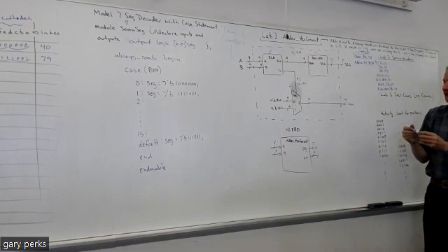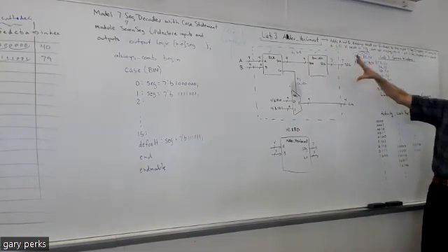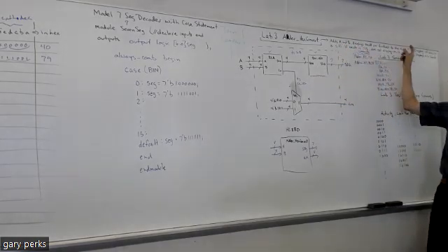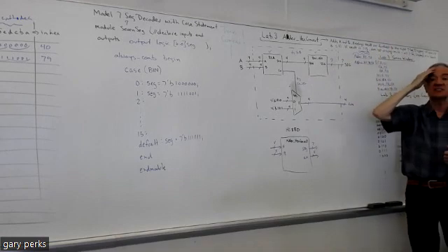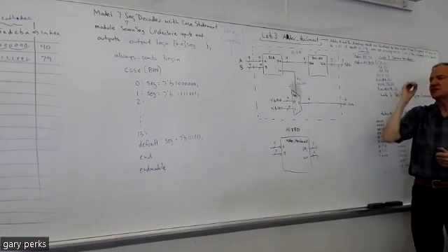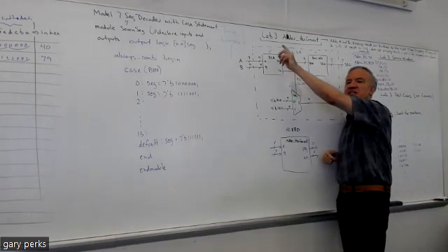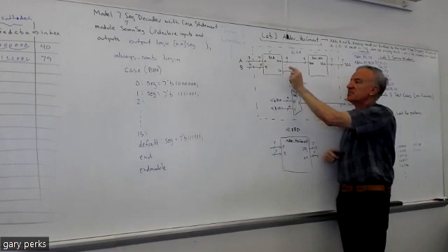All right. So now let's see how this circuit makes this happen. See, the way this circuit is connected, it's going to add A and B and only display the result when the result's less than or equal to 15. Otherwise, it's going to blank the display if the result is greater than 15. So, you all know what the RCA does, right? It's just going to add these two together, show the 4-bit sum here, the carry out here.